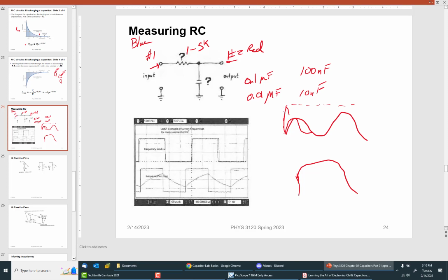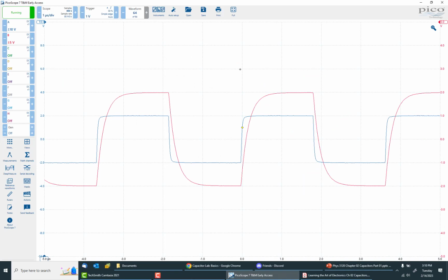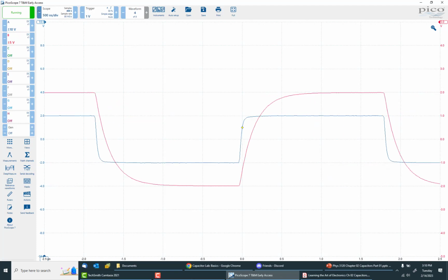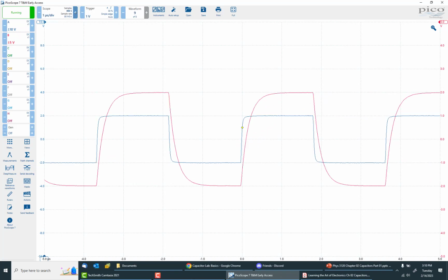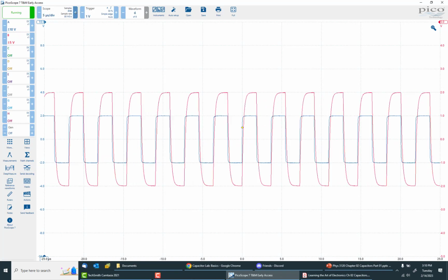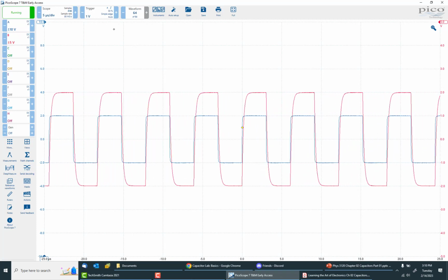This is the first thing they want you to do. You can adjust the time knob. So now I'm twisting it to the right. In your case, now I can lower the frequency here of the square wave.